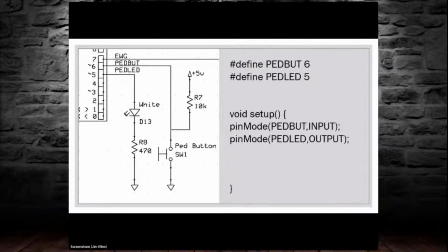As before, the pins and their labels will need to be identified in the IDE. Obviously, there are parts of code missing here, but hopefully you know where to place this new code in the sketch. I didn't explain earlier about the curly braces. As seen in the setup area, the code contained between these curly braces defines and encapsulates that area. Now, it's not uncommon to find curly braces inside of curly braces, and we'll talk about that in just a couple of minutes.